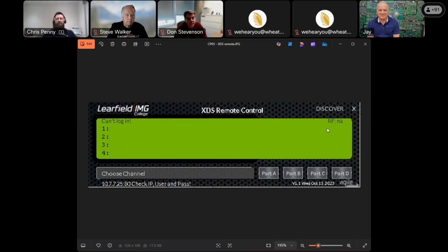So that's a really simple application, but it also shows that we could extend that if someone needed to make a simpler user control. If you wanted to change something from a console in a studio, then you could easily do that by extending buttons on a surface through Screen Builder out into the XDS receiver using the telnet. So yeah, it really does open up options once you start tinkering with this Screen Builder product.